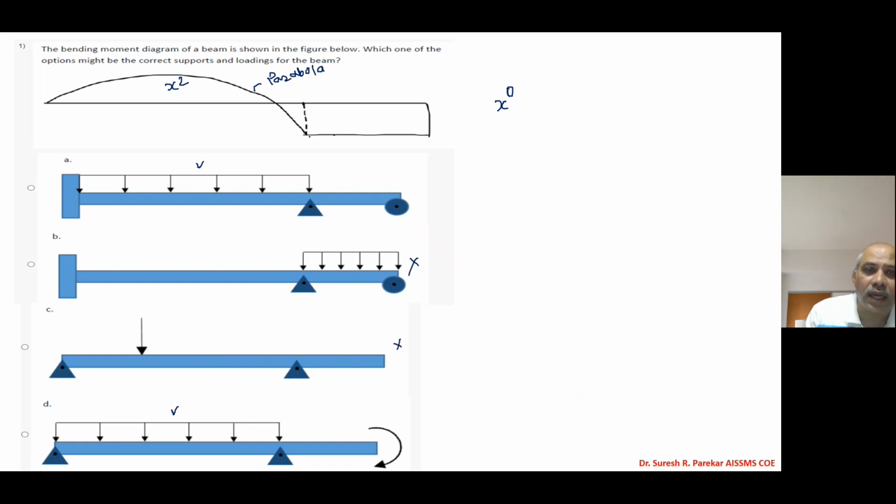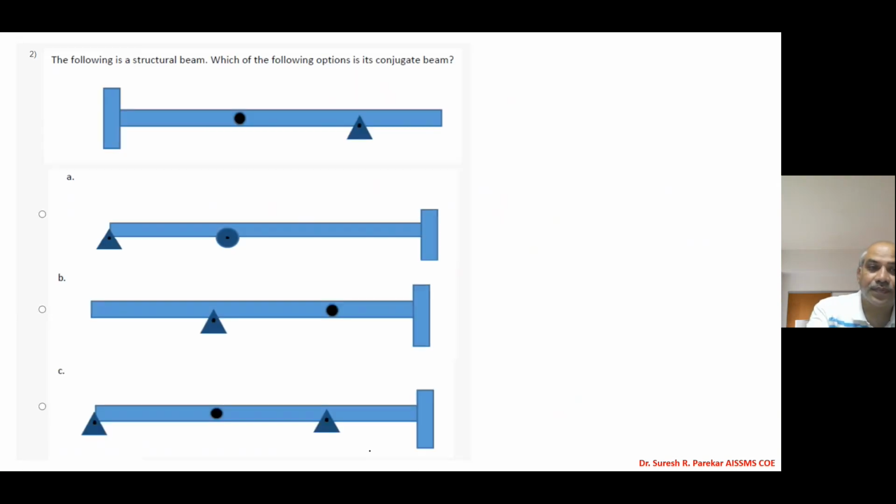Now we are given the maximum value over here, and then we should have here the bending moment diagram. We know we should have bending moment at the end. If I consider this, my bending moment is 0, and a constant bending moment we should have over here, which means we should have D. So we need not calculate the values; we have to understand, and then we are in a position to solve these problems. Because we have constant bending moment in this length, and you can have this constant bending moment in this length.